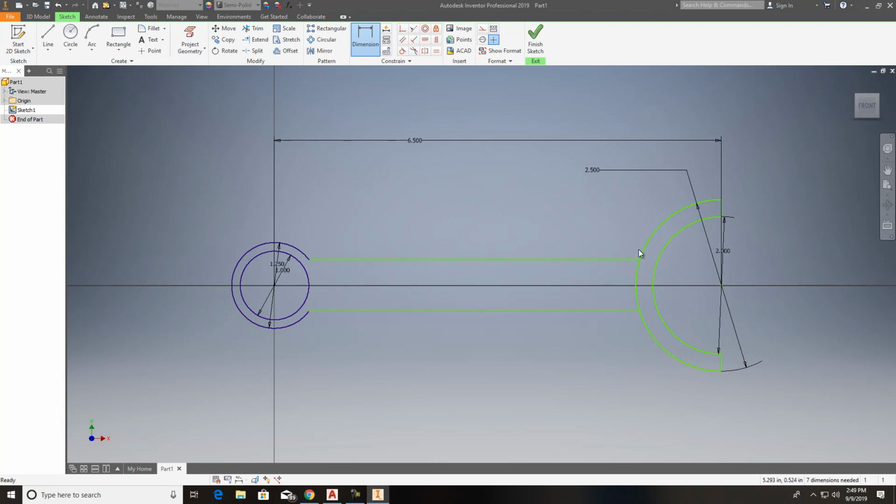Alright, now this thing too looks like it comes up here with a radius on it. And then it's got a little piece up here at the top. So it looks like I want to go from the center of this with a line. I want to shoot this line up 1.5 because it says on there 3. And I want to come over from the edge of it 0.5. And then I want to come over and down. I'm just going to stop it about right there.